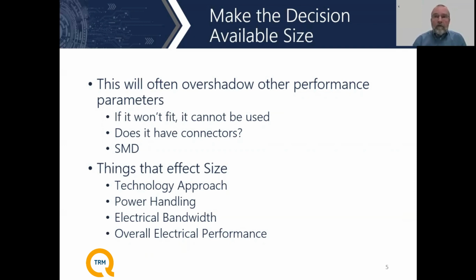A lot of the low frequency ferrite type devices can be quite small. They also can be quite large, and that's really dependent on the power handling capability, or what is required of the system from a power handling standpoint. We make some very small low frequency components that are SMD. We also make some that cover the same frequency range that are 19-inch racks. The difference there being power. One will handle a half a watt, and the other one will handle 10 kilowatts. So there's a tremendous size difference depending on the power handling capability of some of these devices.